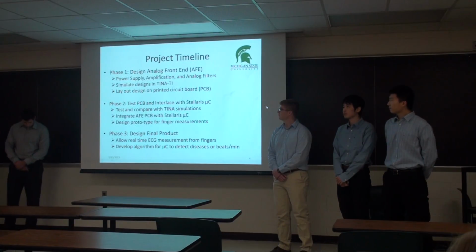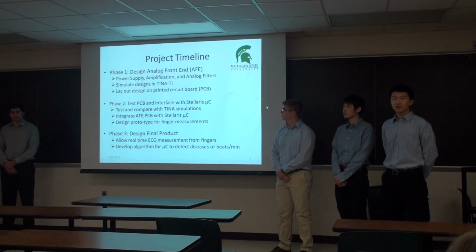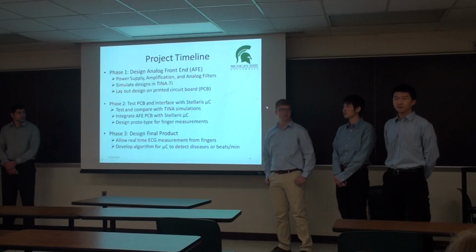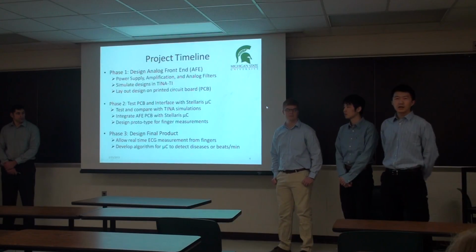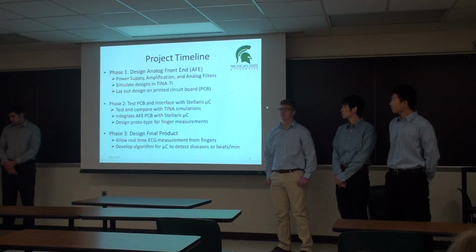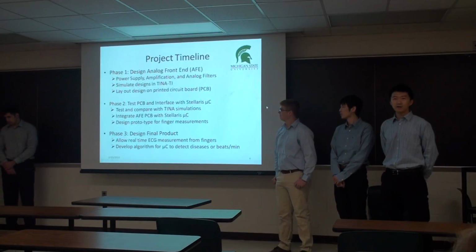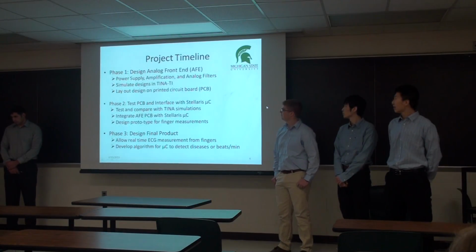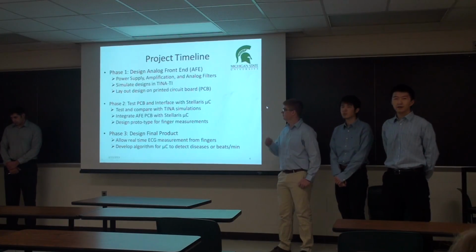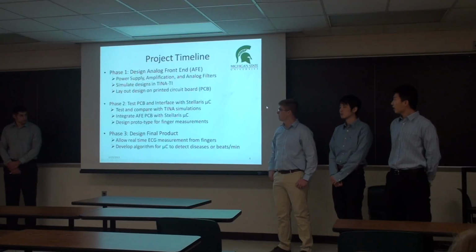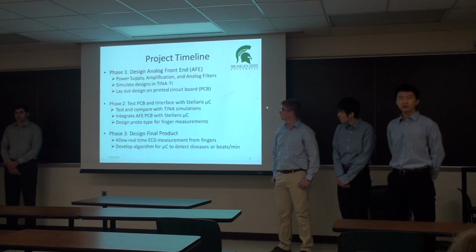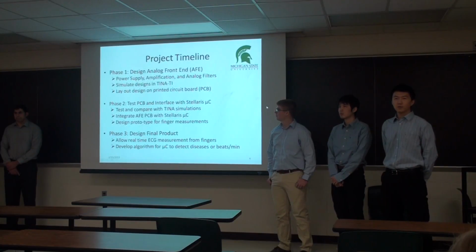And after we complete our schematic circuit, we will put it into TINA-TI to simulate it to see if it works. And according to our schematic circuit, we can design our PCB layout in PCB Artist. Both the TINA-TI and the PCB Artist tools are provided by TI. And once we get our PCB board, we can head to phase 2, which is pretty much to test our PCB board.